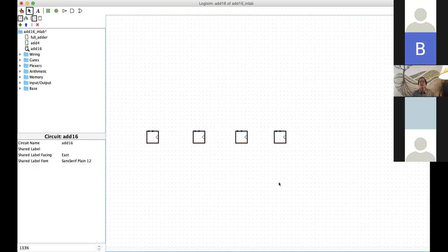Okay, there you go. By the way, if you were to actually lay down 16 one-bit adders, it would be really wide too. This way it's much narrower and nicer, okay? 4 seems to be the right number for a group. If you're making an 8-bit adder, then of course you'll be grouping 2 of them. But if you're making a 16-bit adder and you're going 1, 2, 4, 8, 16, that would be too many levels and too few of them to a level, I think. Okay, 4 is just about comfortable, at least in my opinion.